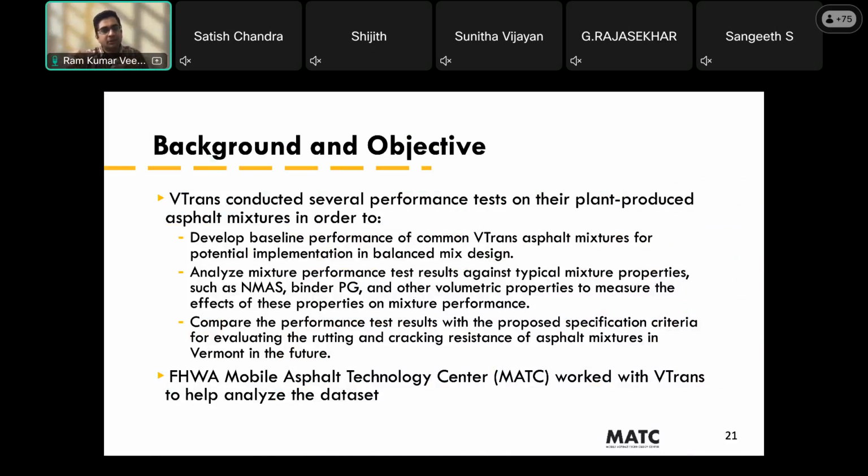So they never went to the extent of aging to simulate field conditions over 10 years. They just reheated the mix, fabricated the mechanical test specimens, and conducted some testing. The data they collected were from the last 4 to 5 years since 2018. VTrans was originally looking at Hamburg wheel tracking and IFIT since 2018, and added IDEAL-CT since 2020.